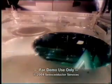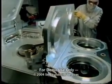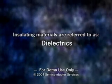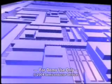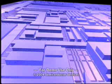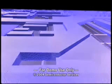Chemical vapor deposition, or CVD, is often used to deposit silicon and dielectric layers. Insulating materials are referred to as dielectrics. Many device structures are built on the wafer surface using CVD layers. This results in height variations that cause focus problems for subsequent patterning operations.